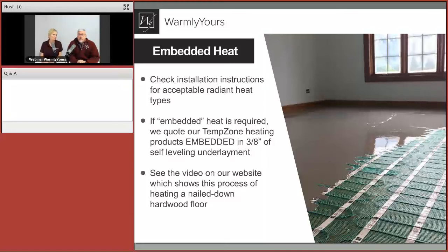Well, this image is our Temp Zone product, and it's under self-leveling. What's great about this type of setup is when we're done, we're going to have a warm subfloor that is completely flat, which means you can pretty much put whatever you want over the top of it because it's like a blank slate that's warm. Maybe we'll put some carpet down here. If I don't like that, maybe in 3 or 4 years, it's in a high traffic area, I decide to go with tile. I can tile over this because I've got a completely flat surface. Or if you decide to go to laminate or whatever, once again, you have a completely flat surface to put the product over the top.